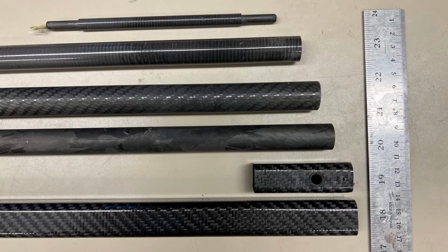And for the last group, you can see they're square in shape, and this is a distinct ability of filament winding, which will also be talked about later. You can see both of these have a 0 and 90 degree layup. And another interesting ability for a square tube is better machining properties. As you can see, a hole is drilled.